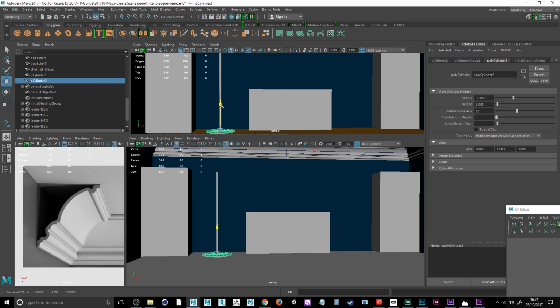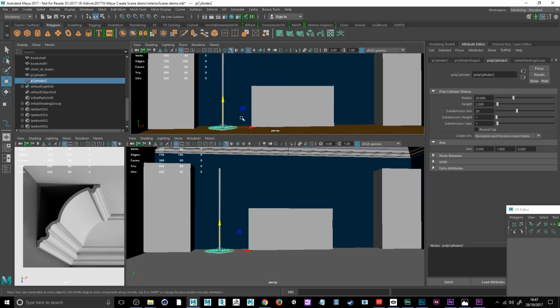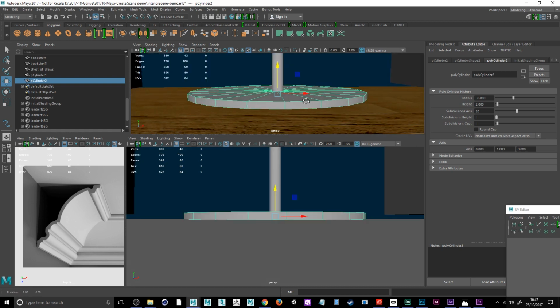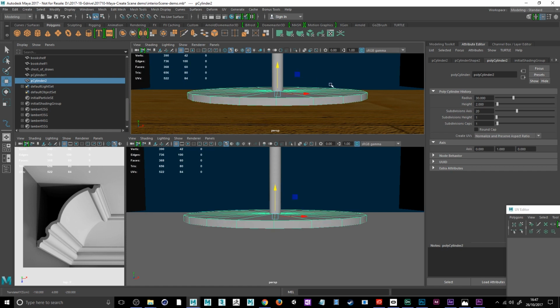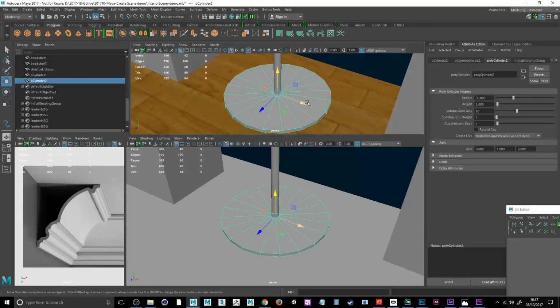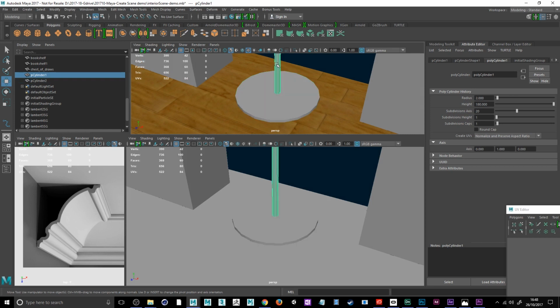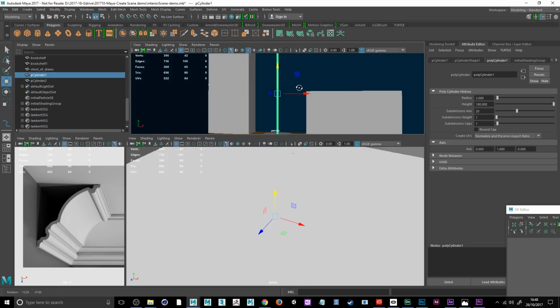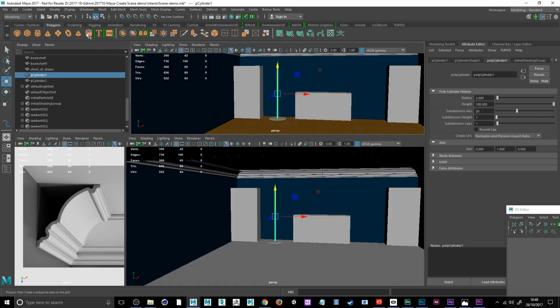So it just needs to come up above the floor, which I'm working to there. I'll press F so that becomes my focus, and I'll just check visually that that's on the ground within that. So it gives me the base. Also for the top parts, if I pick the stem and press F, I should be able to bring in a cylinder or a polygon pipe.